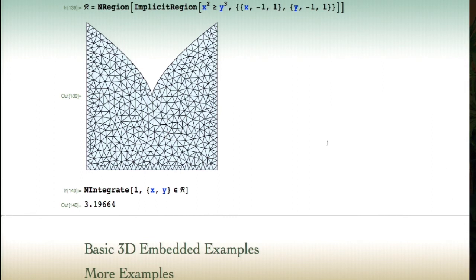One challenge here is that a lot of the things that you've seen in visualization, like region plot and contour plot, are just not good enough to do high-quality computations on. So we are ending up redoing and improving a lot of that because, in 2D, we need to resolve corners of regions really well, or finite element is certainly really unhappy. Or in 3D, there might be creases and other sorts of discontinuities, and we need to make sure that those get resolved really well.